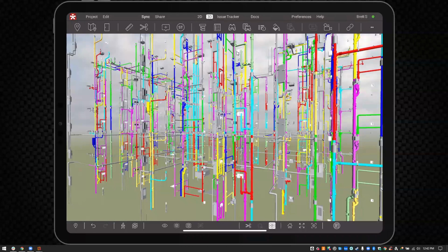So we have allowed the ability to transform these models, hold that transformation. And the best part about this is if it is Revit information, we are going to also transform the sheet. So it's more of a file transform than it is a model transform. So, very interesting. We intend for the workflows to totally shift towards a federation inside of Revizto, especially as we encroach upon including our clash detection module.